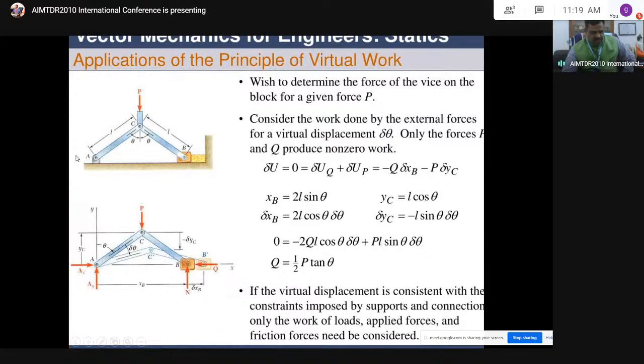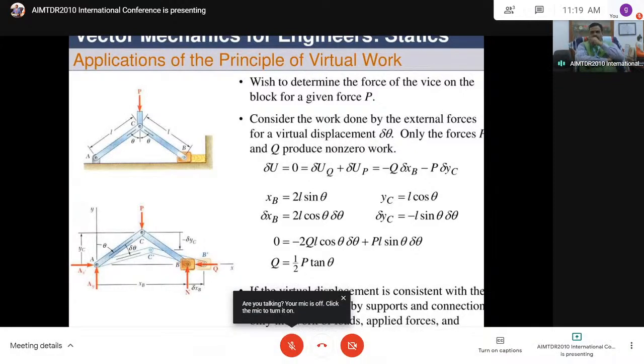Now we have a hinge joint with two reactions, Rx and Ry. This is something like a translating joint; this is a pin, but here it is a vertical reaction. That's what we are considering: external forces, active forces, reactive forces. We are not considering any internal forces because it is a rigid body concept. If it is a deformable body concept, that also we have considered. Now we have to consider the total work done. Here the work done is only due to the constraints.